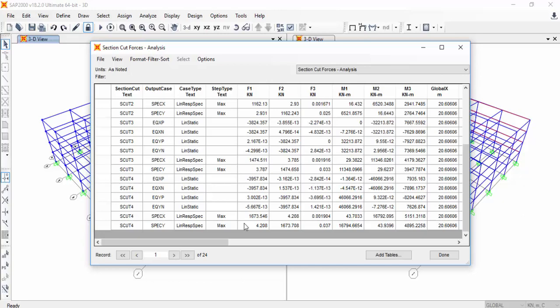Now we find that the earthquake forces computed from static analysis and dynamic analysis are very different. But that is expected because in the dynamic analysis, the time periods are generally much longer than what the code prescribed time period formulas mention.